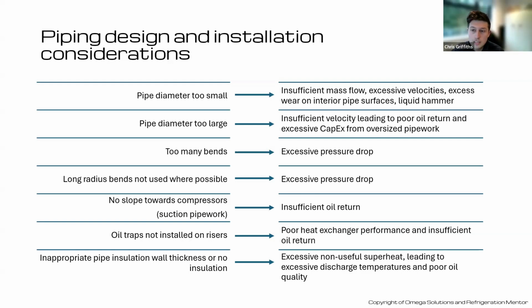Yes, definitely. So, for example, in a supermarket, if you've got a long pipe run and it goes through from the sales floor over a bakery where there's lots of ovens, unless you've accounted for that in your design, you could effectively double the amount of heat being added to that pipe, because our temperature difference has gone from 20 degrees Celsius up to a sort of 40 degrees Celsius into our pipe work, even more so if we're, again, working with low temperature. It's just a case of not just copy and paste from a previous design you've done, actually look at where that pipe is going to go and account for it as well.